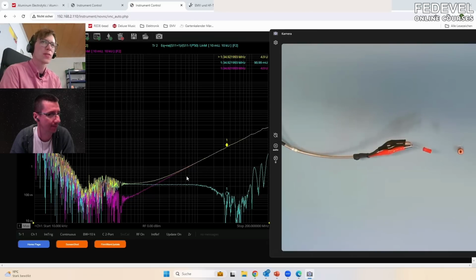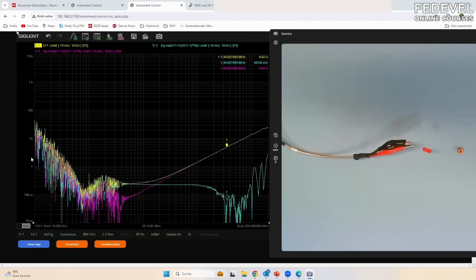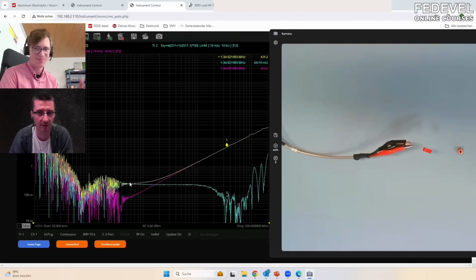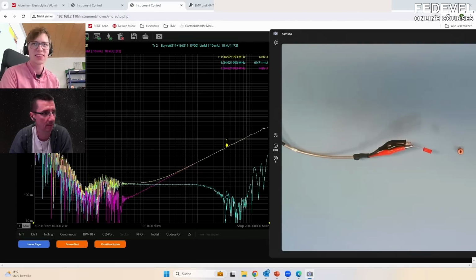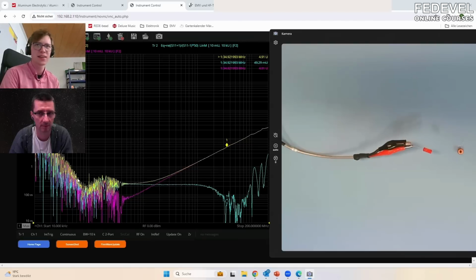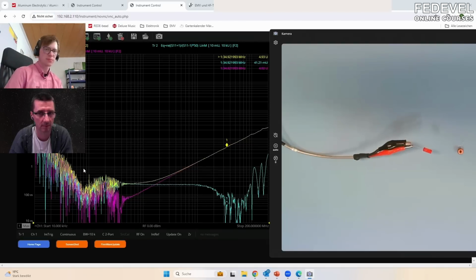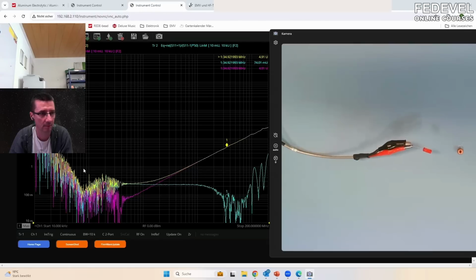And here you can also see the limits of a measurement device because I need more power. I cannot see this area here. You see it is quite noisy, and this is not valid up to this point here. It was actually my question, like why is it so noisy there? Yeah, I'm sending there with 0 dBm of power, and you're looking for the reflection. And there is no reflection. It's actually at this frequency, also the coupler inside, and also I have here, maybe you can see it, the limiter.